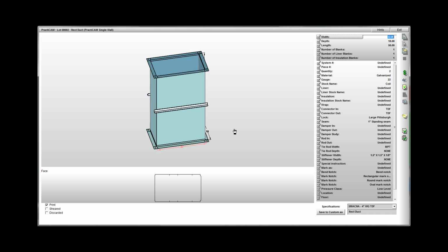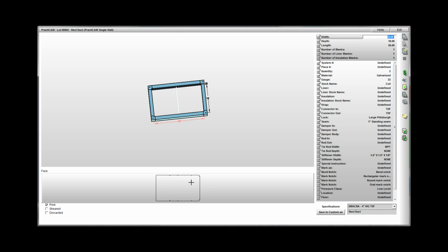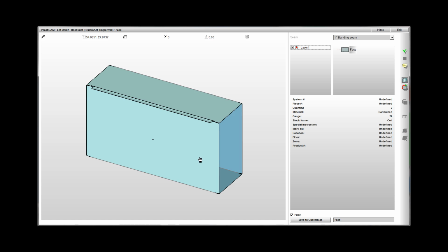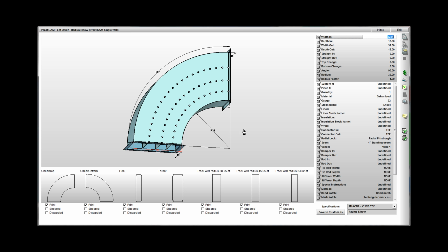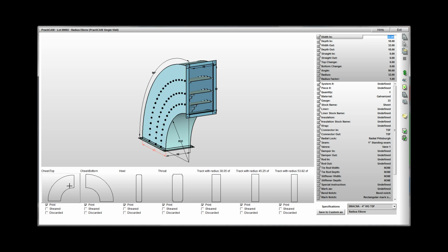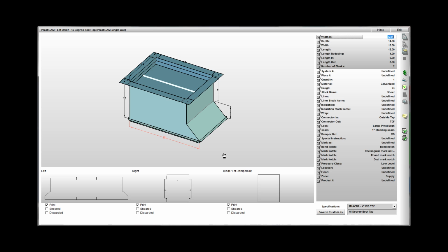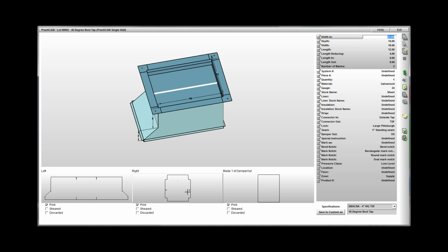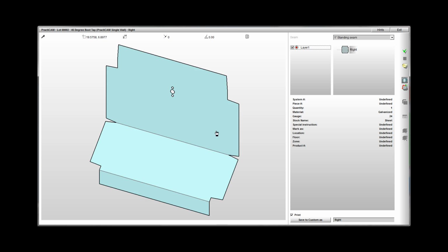This includes our vast library of accessories. Stiffeners will come across for reporting. Tie weld holes are burned by the plasma or punched by the coil line. Splitter vanes are automatically cut in radius elbows, including drop cheeks, as well as the holes are burned for tack welding for those that choose this option. Damper blades are cut with everything we need, including U-bolt holes or earless. Even the damper shaft insert holes are burned by plasma.